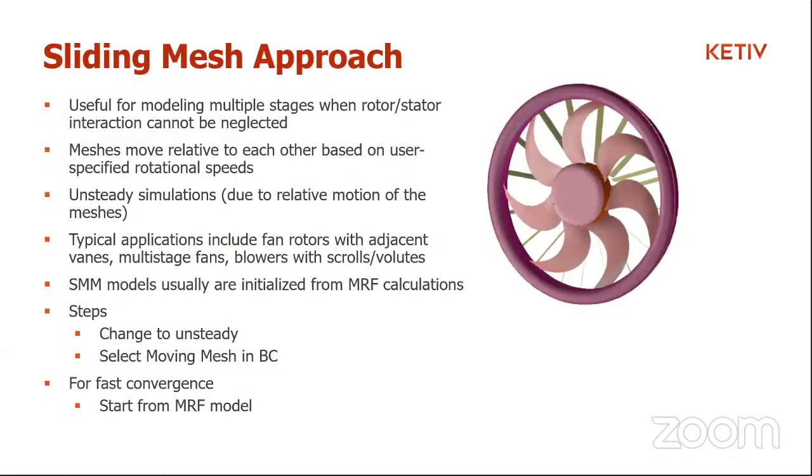And then you have other approximations as well, apart from moving reference frame. For example, the sliding mesh approach, wherein you actually specify a zone that is sliding with respect to another zone. And this sort of approach can be very simple to set up as well, provided that you have axisymmetric conditions, provided you have surfaces of revolution. If you have random solid stationary walls within your fluid zones, then there might be an issue using this particular approach.